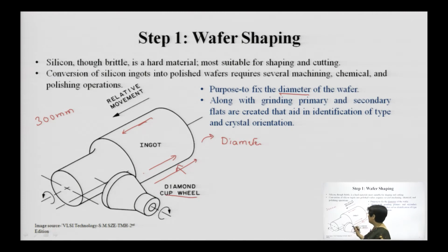It is a brittle substance, we have seen it is a delicate substance, that is one of the drawbacks of it. But then there can be a possibility of chipping, or there can be a possibility of cracking, edge cracking, or any other cracks which are because of the orientation of the crystals. Now, that you need to avoid. So, therefore, there is a lot of precaution to be taken while handling this grinding process. So, all chipping, cracking, that has to be avoided, and you need to take a lot of precaution in grinding. So, this is about grinding.